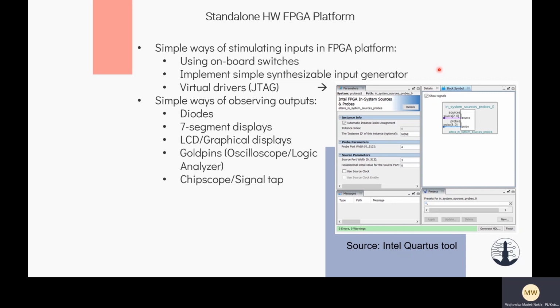You can also implement a simple synthesizable input generator apart from your main design that is going to work as another piece of hardware. And the goal of this generator will be to provide, cycle after cycle, some pattern that is going to go into the inputs of your design. And that way we have two synthesizable blocks, of which one works as a driver and your DUT works as a receiver. And then when these patterns are being provided, you can observe how your outputs are going to react to it.